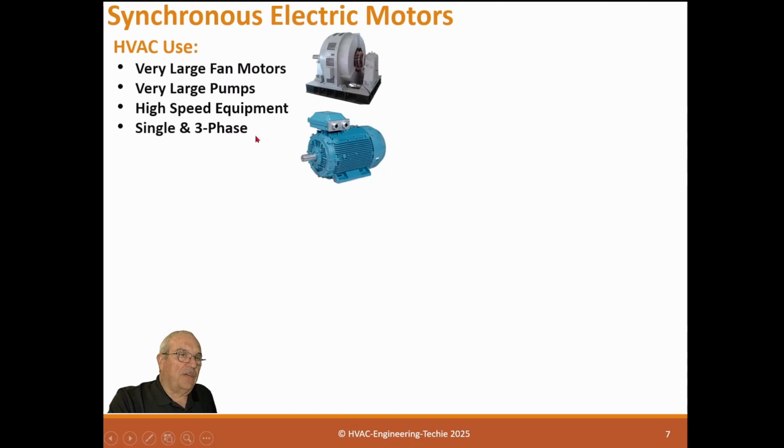Single phase and 3-phase on synchronous motors. Very small motors. They also have very, very tiny motors. And the reason these small synchronous motors exist is because they always go the right speed, and they use them for clocks. If you have something that's timed, like a gear motor, that has to be timed to a special speed, they'll use a synchronous motor because they can always guarantee the speed. Whereas on an induction motor, depending on the amount of slip, it'll be off slightly. So that's why they use synchronous motors. You may have some of these, but you won't quite know where they're at, but they could be on your job.